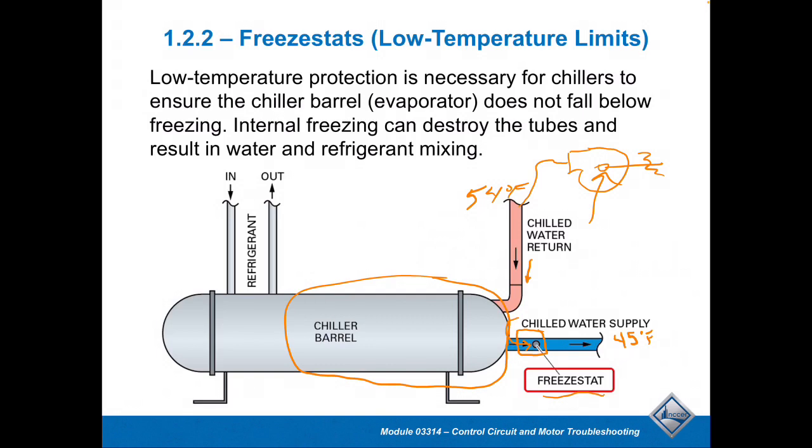So you might cut it out at 35, 36 degrees. If you're running glycol, which maybe has freeze protection down to 10 or 15 degrees, you may normally be running a temp on that glycol loop as low as 20 or 25 degrees. That being said, you would have to make sure that the freeze thermostat is adjusted for what you're trying to protect.